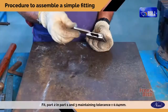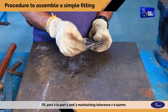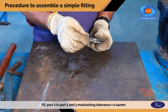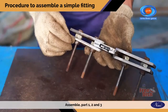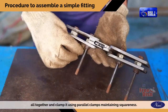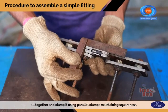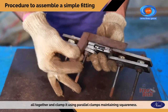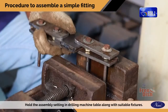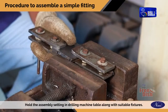Fit part 2 in part 1 and 3, maintaining tolerance plus or minus 0.04 millimeters. Assemble part 1, 2 and 3 all together and clamp it using parallel clamps maintaining squareness. Hold the assembly setting in drilling machine table along with suitable fixtures.